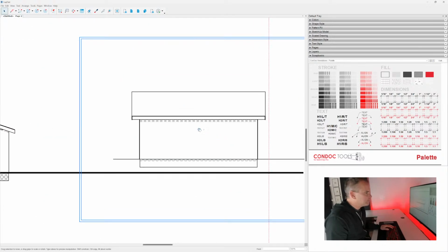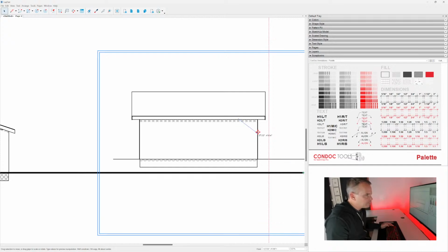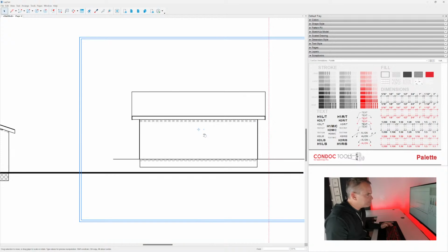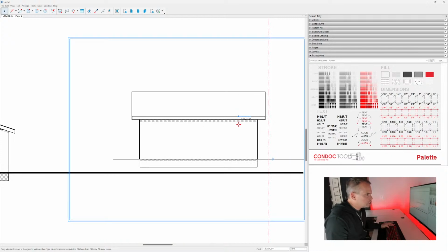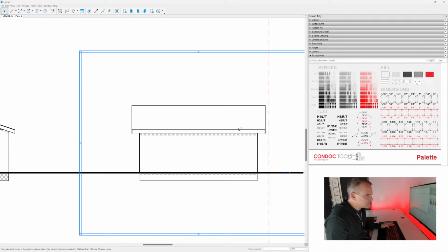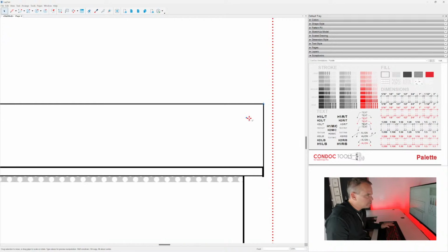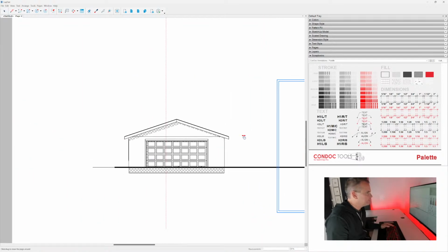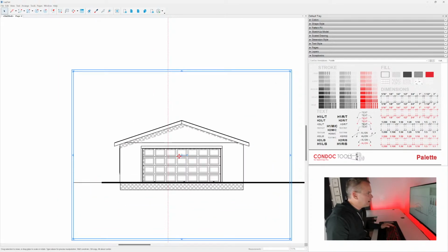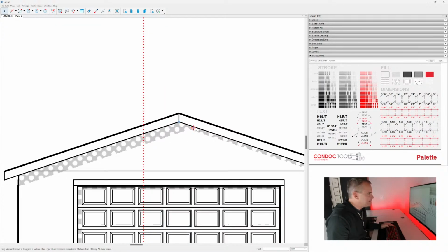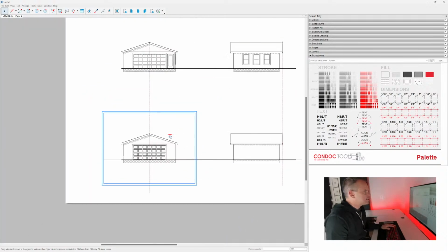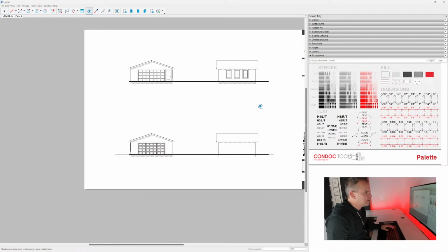This guy over here, perhaps I could take the precise move grip and move it using that left little circle or grip. Hover on the drawing, and now, let me undo that. Snap there, hold shift, and now I can move it straight down and snap. Next, I'll put it on that little roof there, and then snap over to there. Now on this guy, that one's all set up on the base plane, and then I can move it, hold shift, snap to that little guide I created, and we can get rid of those.